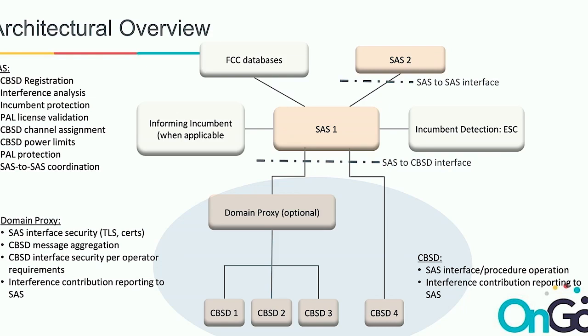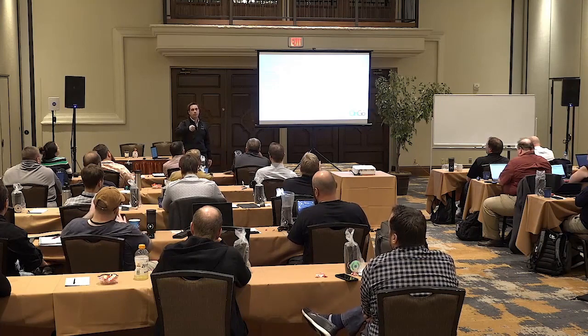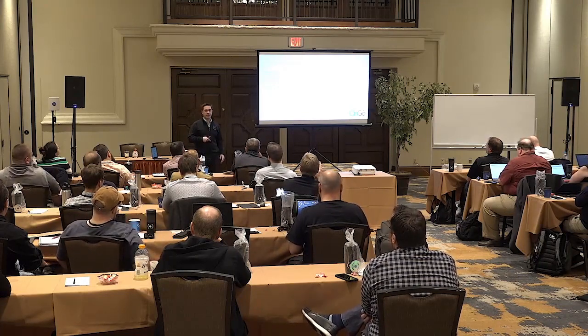As an enterprise, you really just need to think about the lower portion with the radios and the domain proxy functionality. The question is, are the SAS providers geographically segmented? No. All 5 of them can operate. They can control any and all portions of that 150 megahertz.